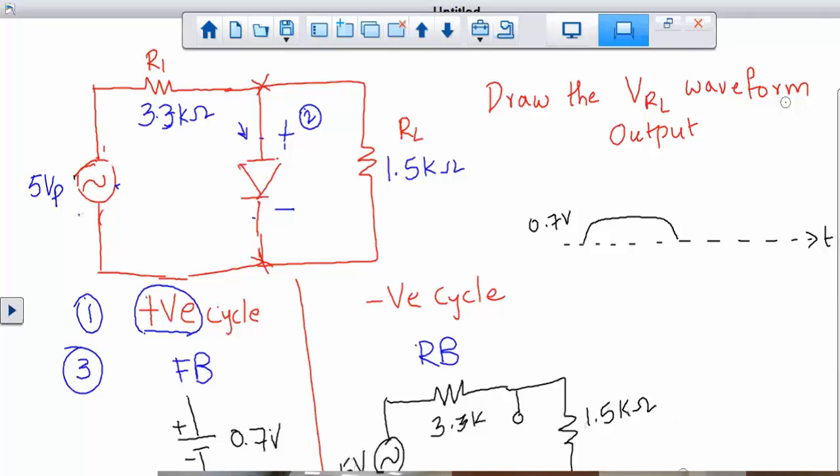So the voltage on this load resistance, the 1.5K, the interested resistor, is 1.5K over the total resistance, 4.8K, which is the addition of those 2, times whatever the source voltage is. Again, remember you're performing this for the negative cycle. So the outcoming voltage would be negative as well. So whatever that voltage limit would be. So how much did it come out?